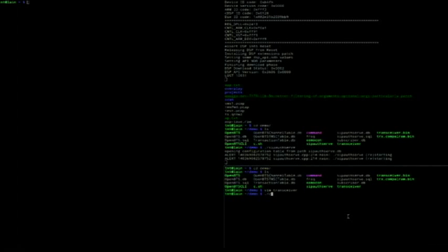And then you need to select the frequency at which you want to broadcast. You should only broadcast, of course, on a frequency you have a valid license for. We have a license here, 869. It's currently in use, so I'm just trying to broadcast stronger than the network in here, to see if hopefully that works.